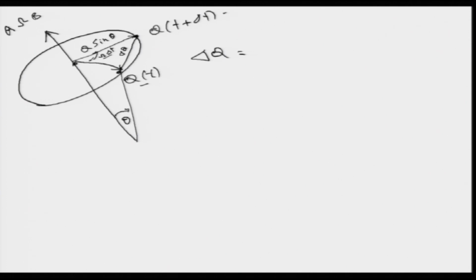So, it is equal to q sin theta and then omega a b into d theta into dt, sorry, right. So, this is the distance del q which it has moved from here to here in time dt. Okay. So, this is the linear velocity, which is the linear displacement you can see from here, and this is because this body has been rotating about the axis by having an angular velocity a omega b.